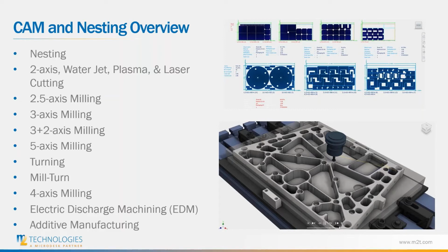However, you are not able to rotate the workpiece while performing milling operations, which leads to the 5-axis milling, which allows for fluid motion in all 5 axes in order to perform unique geometry constraints and have the most flexible cutting options.